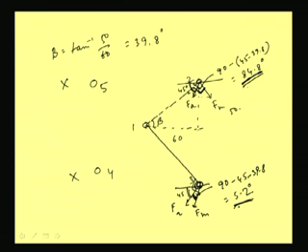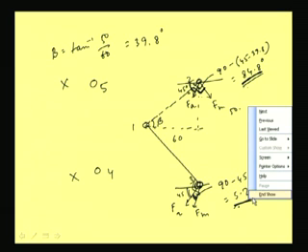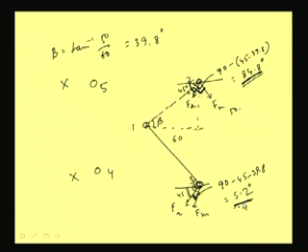The lesser the angle between two loads, the more the resultant, because Fr is basically root over Fa square plus Fm square plus 2 Fa Fm cos theta. Now, cos theta will be 1 if theta is 0. So, here if theta is less, cos theta will be more.